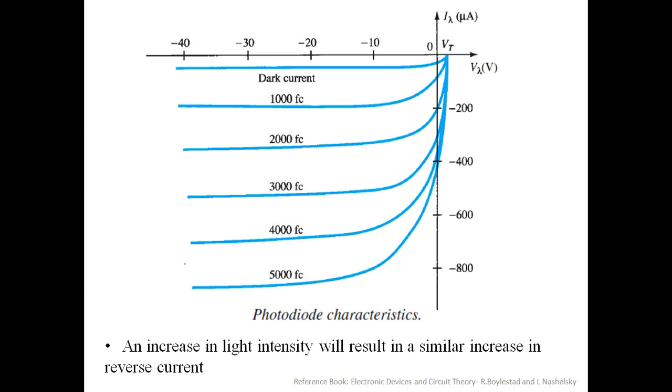This is how the current through a photodiode looks like. I had just mentioned that it's not a forward current, it's a reverse current, right? Okay, so just observe. If it was a normal diode, you know how a normal diode functions. In the forward bias, it is exponential current. In the reverse bias, there is a very, very small current, minute current, and then suddenly there is a surge of reverse current due to the breakdown. Now, if I just focus on this point, this is the reverse current before breakdown, which is extremely small, right? Okay. So, the same is being taken here.